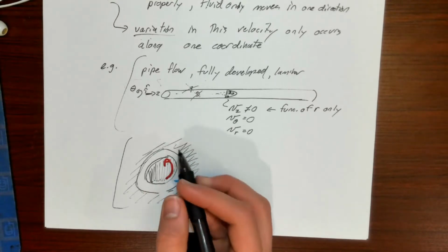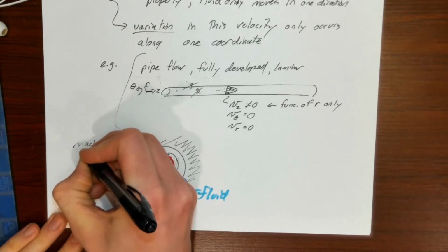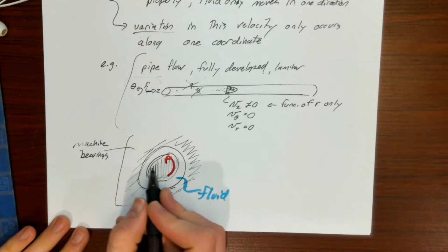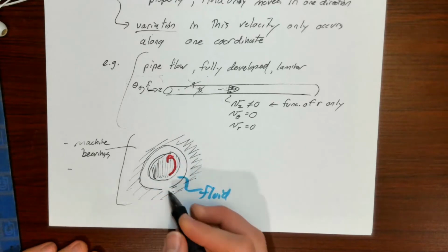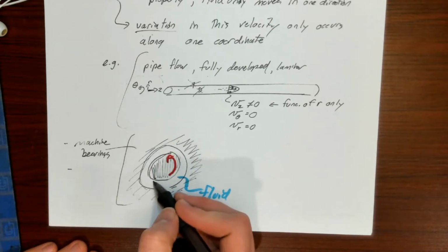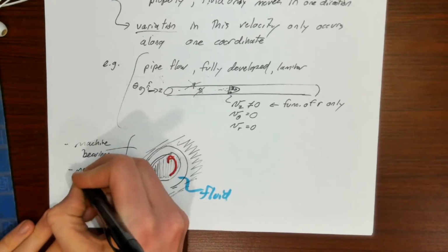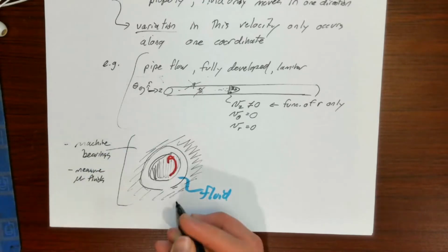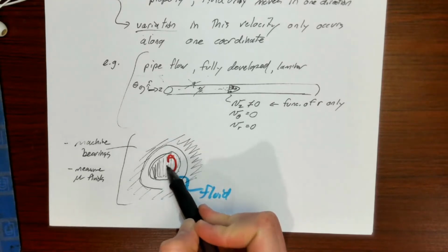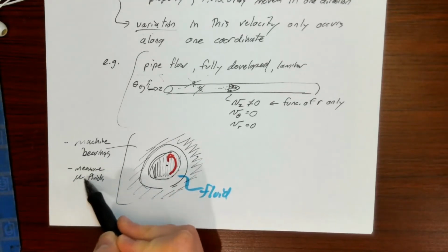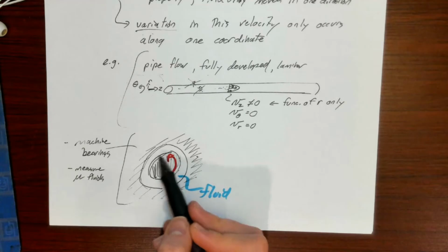Machine bearings often look like this. And then also, sometimes people intentionally design devices like this where you can squirt whatever fluid you want in between these two things and use it to measure viscosity of fluids. So you can use the fluid as a lubricant between a part of your machine that's moving and a part that's not, or you can squirt some fluids in and measure how much torque it takes to smear the fluid around.